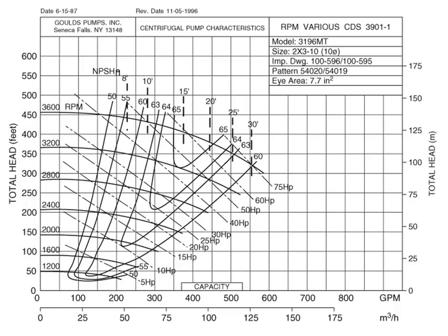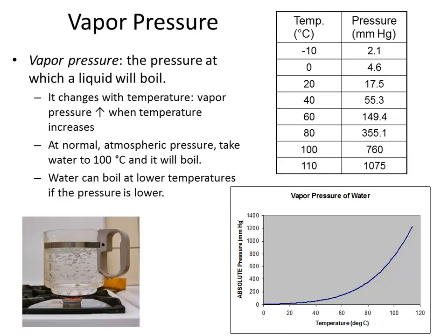And so the reason why they have these specified amounts of net positive suction head is they know inside the pump what's happening when you've got 550 gallons per minute going through the pump. And so these varying levels of net positive suction head that's required is because they have an understanding of what the relative pressure differential is inside the pump itself.